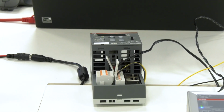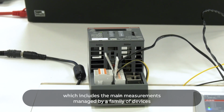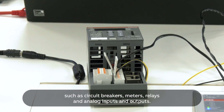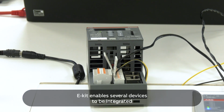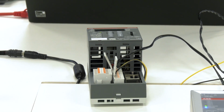correctly. Model creation starts from a generic template, which includes the main measurements managed by a family of devices, such as circuit breakers, meters, relays, and analog inputs and outputs. E-kit enables several devices to be integrated by means of the Modbus RTU and Modbus TCP/IP protocols.